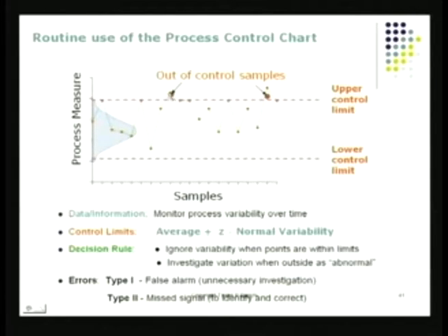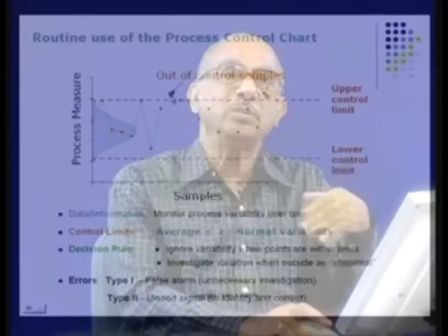Don't second guess. The moment the chart has gone beyond control limit, stop the process and go to something that is called the reaction plan, which is what you construct using the cause and effect diagrams and so on. Then go through your full list of checklists, and check everything about that machine, just to make sure that you do not end up thinking everything is in control, and end up producing products that are off spec.